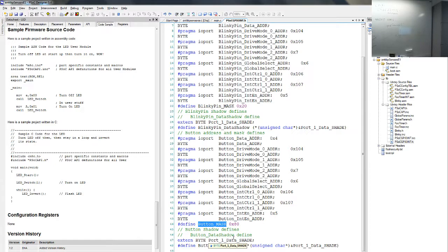It's 8-bit data, so it also shows every other pin on that port. You need to use the mask to select only the pin you are interested in. And there you need a little bit fancier operation, bitwise operations, bitwise masking.